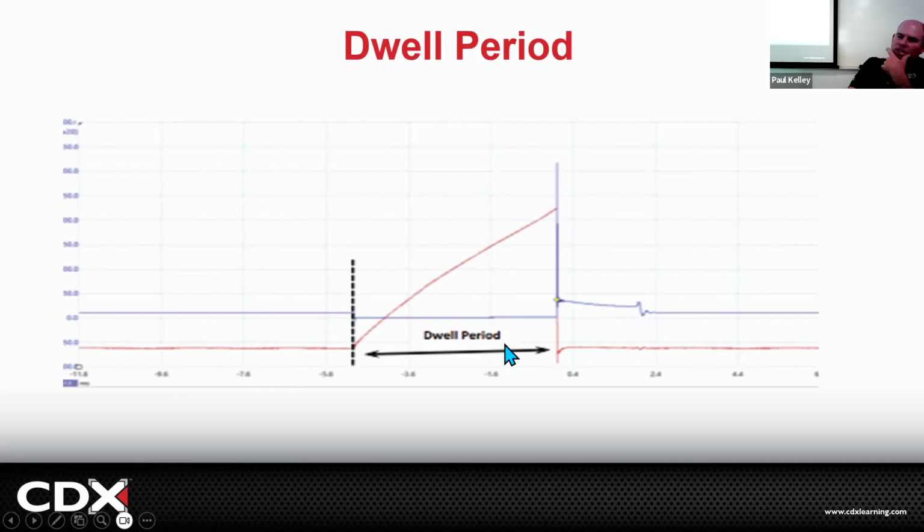But the thing is, to measure it, you know this screen right here, this is actually on the oscilloscope. So if you wanted to measure the dwell time, you'd have to hook this up to the oscilloscope and physically graph it. And then you could determine how many milliseconds this is based on your settings and be like, oh yeah, it has this much dwell time. For example, if this is ramping up nicely, that ramping up nicely tells me that the primary side of the coil is working. I'm not going to set a primary circuit code because it's ramping up nicely.